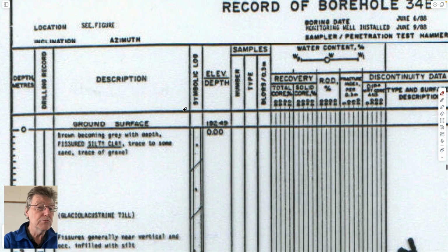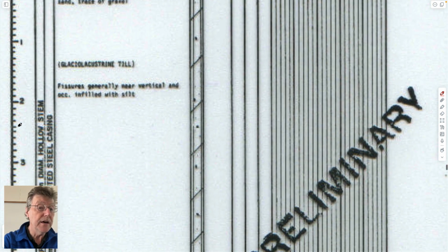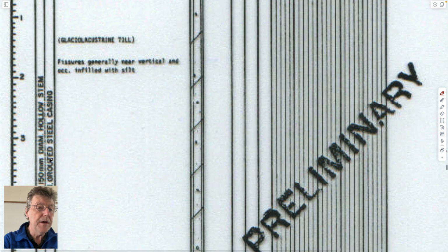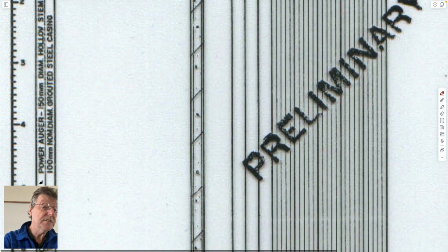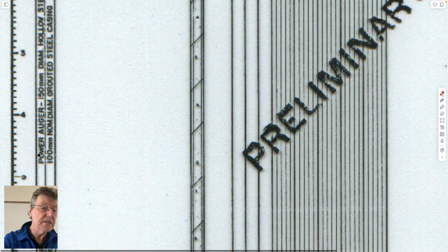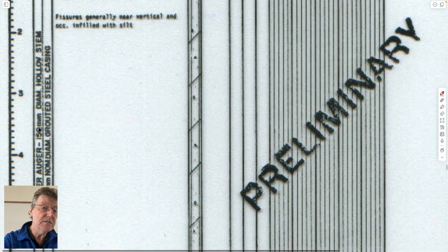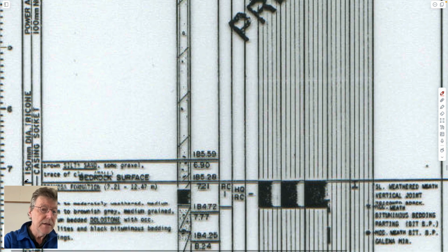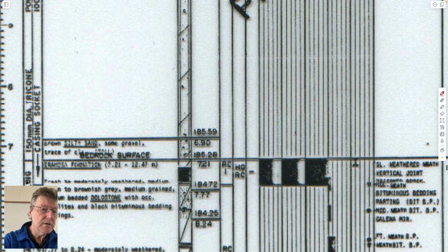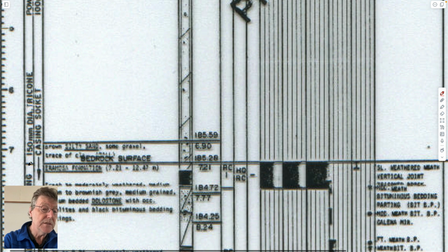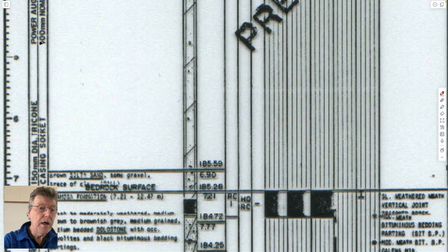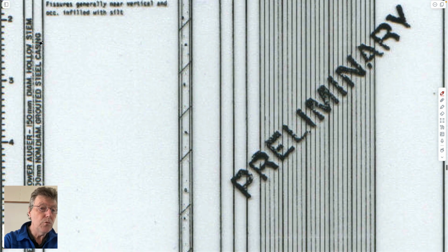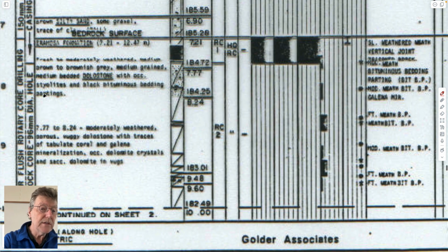And so typically things would be recorded with depth as you go down, from the methods of advance. So here in the left-hand corner, this is actually for Smithville. And the information here is the method of advance on the left-hand side. So auger, 150 millimeter diameter hollow stem auger to get through the soil to some depth. And then from then on, drilling with a tricone to get down to the beginning of the rock. Then applying casing into it, maybe by widening the hole and putting casing. And then drilling through that casing with a rotary drill to be able to sample the rock.